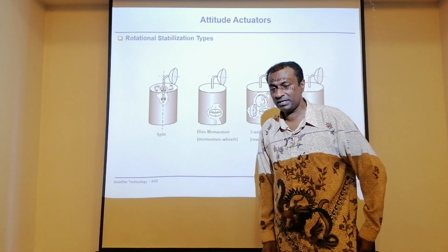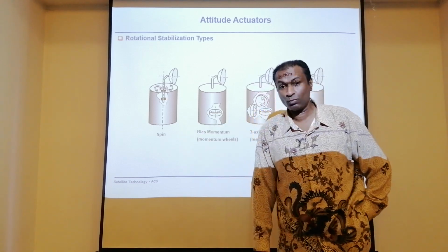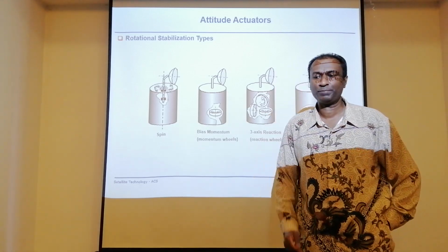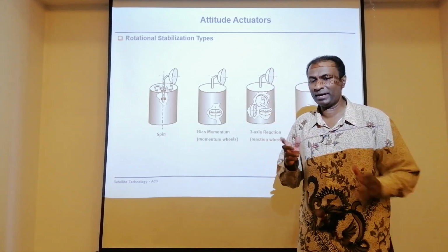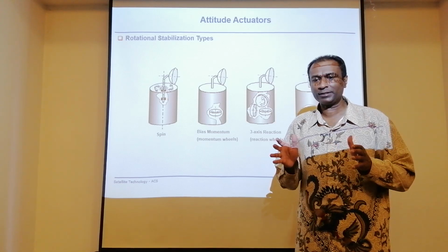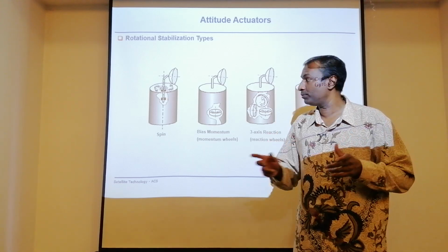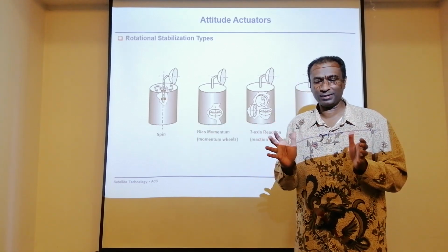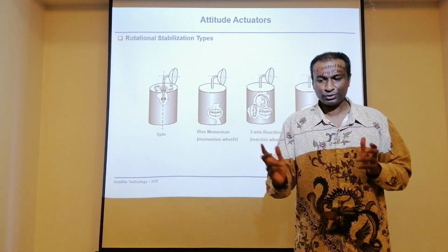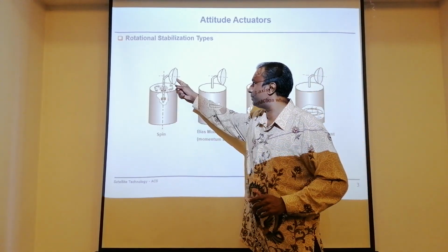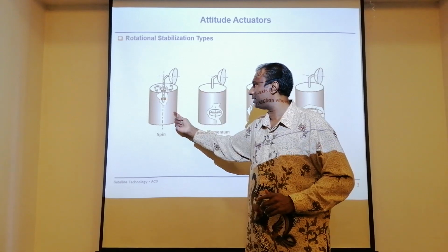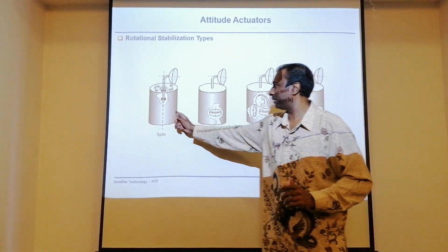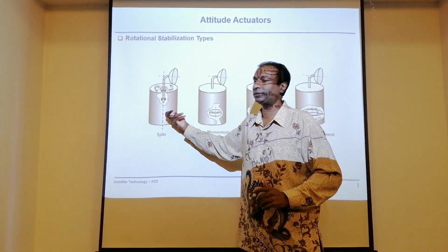This is quite a primitive way. In fact, Nyasat 1 is being stabilized using spin stabilization. That means you can imagine that it cannot be a cubical rigid body. It has to be a good cylinder, a symmetric cylinder, better still, and you spin the whole body. The antenna will be looking at planet Earth, for example. The whole body is spinning. So this can be also done by spinning and stabilizing the whole satellite.